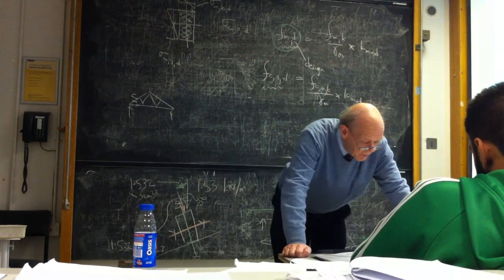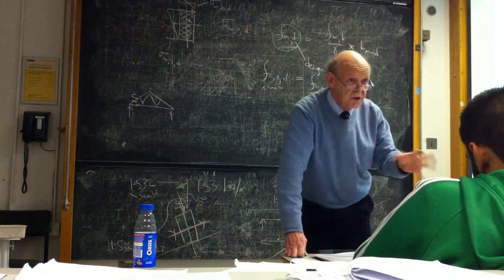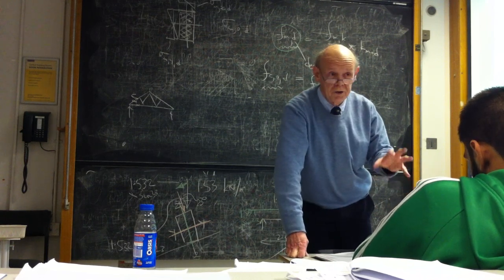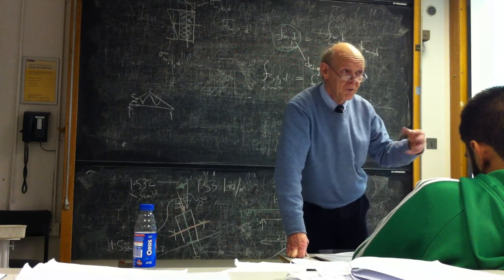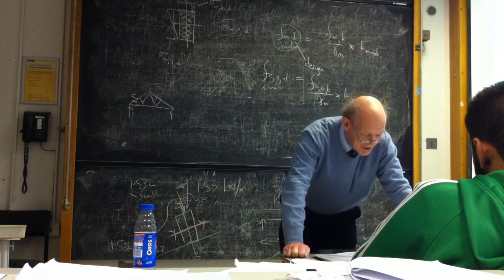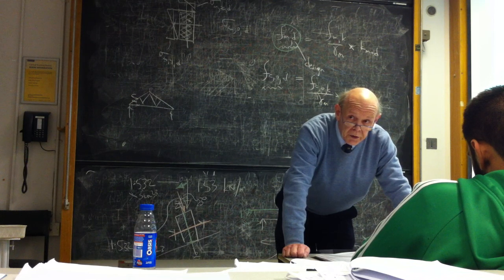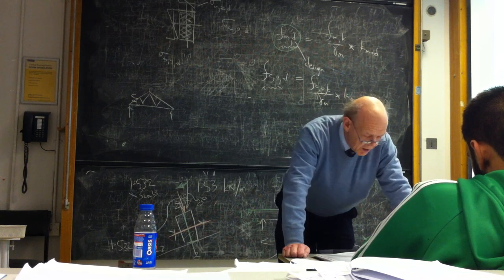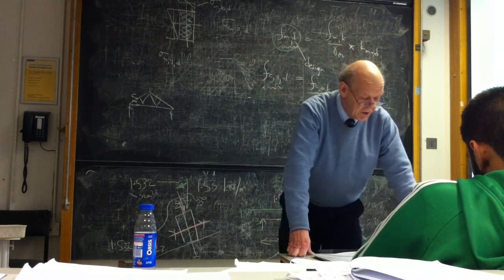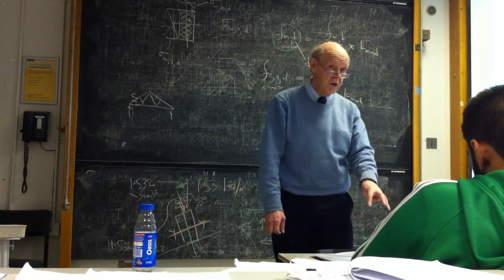So the next thing that they've got is a series of things they call the buckling factors, and this is what this huge piece of theory in the notes was all about, which you can forget and read up and impress your boss when you get a new job sort of thing, but in the meantime you can forget it. They first of all ask you to find out a coefficient called ky if it's buckling about the y-axis, and kz if it's buckling about the z-axis. Now, since we've got both of these situations happening at once, you've got to do each one.